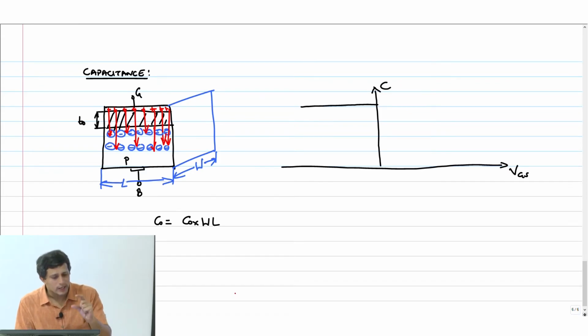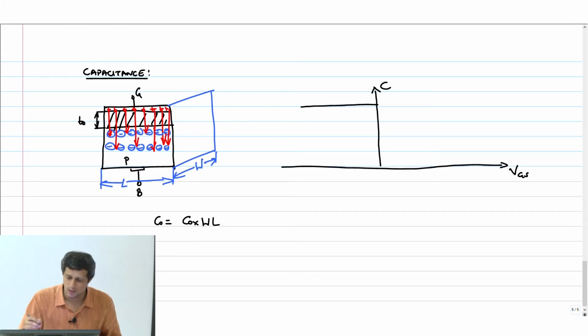So therefore, if you look at the capacitance in this depletion mode, it is going to be the capacitance of the oxide in series with a depletion capacitance. Obviously, if you put two capacitances in series, then it drops. It's C1 C2 by C1 plus C2, and therefore this capacitance will now drop.